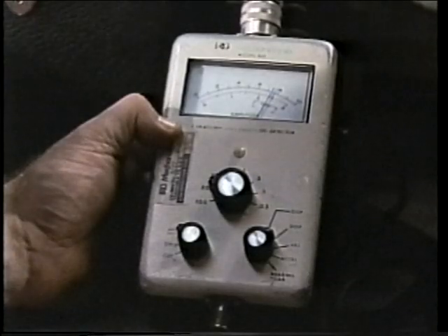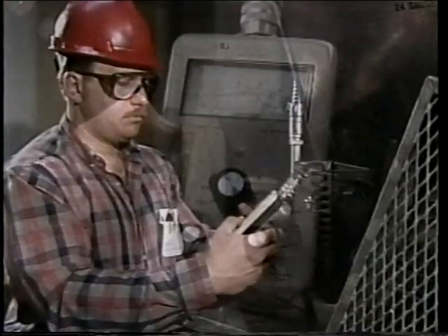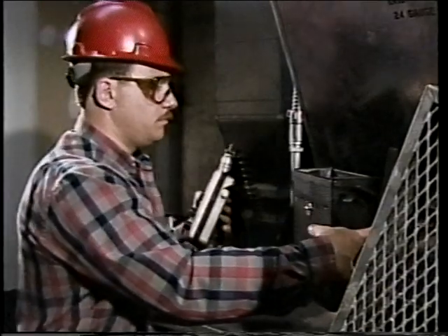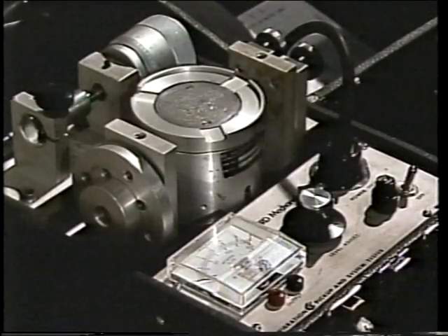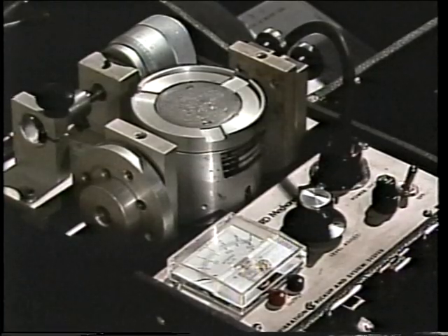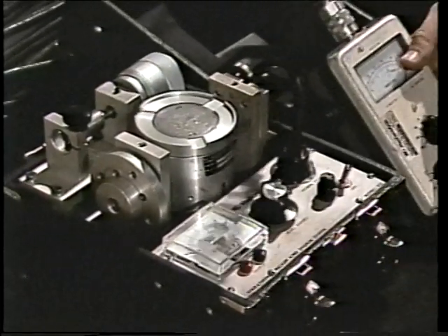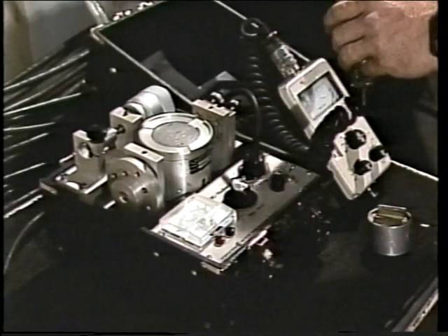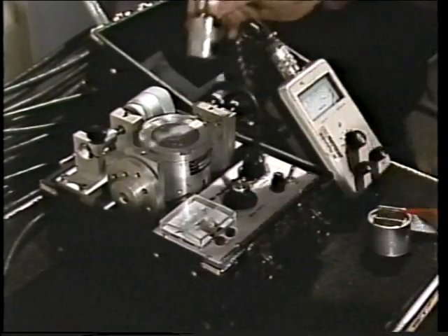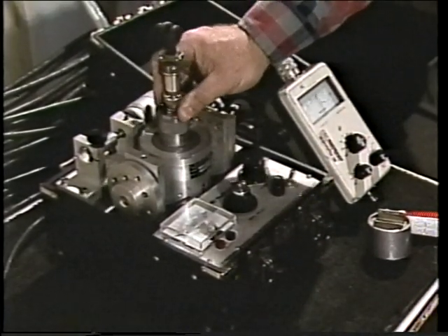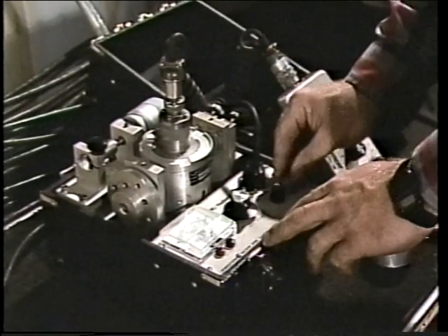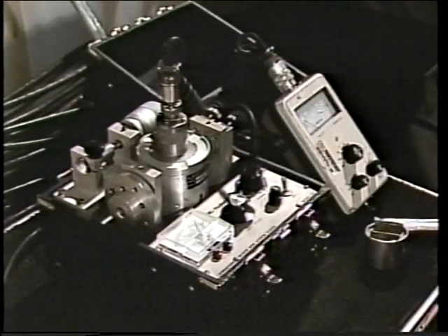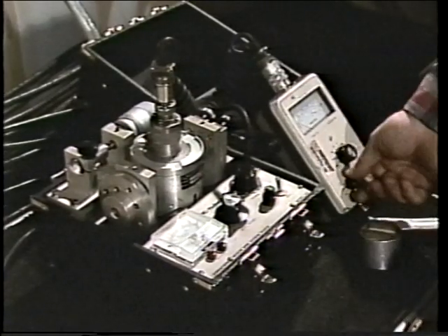After the batteries have been checked, the instrument can be turned on. Many meters have a keypad or switches to turn them on and select specific functions. If the instrument needs to be calibrated, then it should be done at this point. Many instrument manufacturers recommend that meters be calibrated at least once a year to ensure their accuracy. This can be done by using a calibrator, which is commonly referred to as a shaker or shaker table. A calibrator produces a vibration that has a known frequency, displacement, velocity, and acceleration. By placing the meter pickup on the shaker, a meter reading can be taken. That reading can then be checked for accuracy.